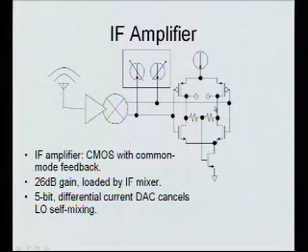And the only real cool trick here is the way I do common mode. So I have a source up here, so this is essentially a diff pair we're looking at. This is a diff pair too, but instead of having a pure current source here, this device is actually in triode, and its resistance is set by the common mode. So you can imagine if the common mode rises, that turns this device on more, which makes it draw more current and brings the common mode back. And so automatically the common mode of the output is fixed sort of in the middle of the supply range. It's not precise, but it's pretty good. So then we have a nice differential amplifier with a really high output impedance and common mode maintained.